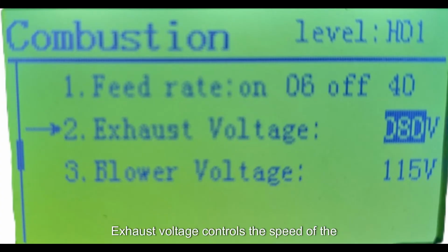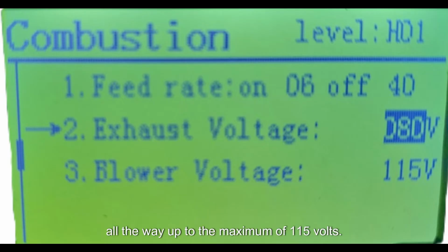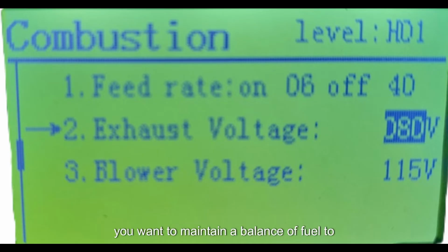Exhaust voltage controls the speed of the exhaust fan. The higher the voltage, the faster the fan spins, and the more air that is pulled through the system. This voltage ranges from 80 volts at the lowest all the way up to the maximum of 150 volts. This is typically tied to the feed rate, as you want to maintain a balance of fuel to air for proper combustion. A good rule of thumb is this: if pellets are shooting out of the burn pot like an active volcano or popcorn machine, the exhaust voltage is probably too high and needs to be decreased. If the fire is lazy or a darker red or orange color, then the exhaust voltage is probably too low and needs to be increased.